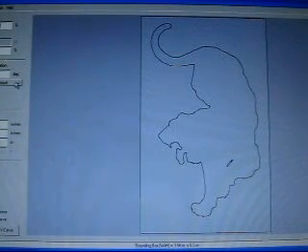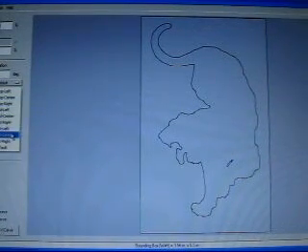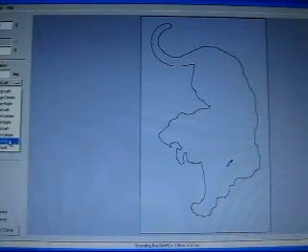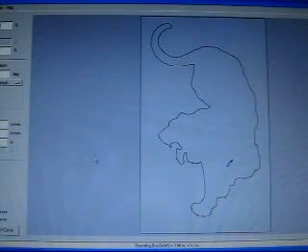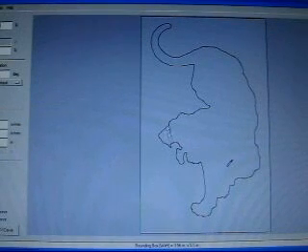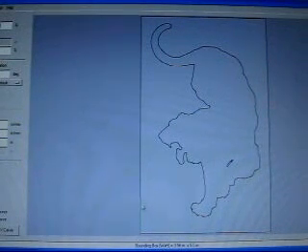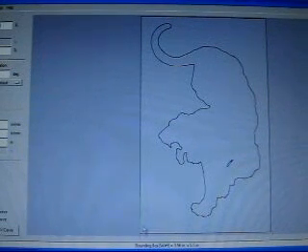Just so you know, there's a difference between bottom left and default, even though it is at exactly the same location. If I had it at a different location, like out here somewhere, and I pressed default, you would see the 00 would be here instead of on the bottom. But since we created it in Inkscape to be on the bottom by that alignment technique, it is here. This is our 00. You always want to be aware of that.